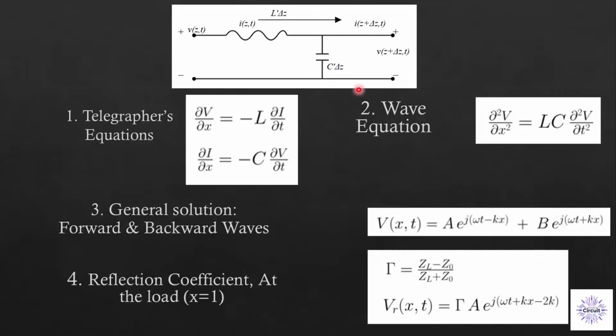Basically, what we want to do is that now a track or a wire is not just a wire where the voltage across it is equal. The voltage may be different if you look at different points on this wire. And one of the ways to model this is using transmission lines, because now the wires are transmission lines, and as the voltages travel across them, their phase and their amplitude change.